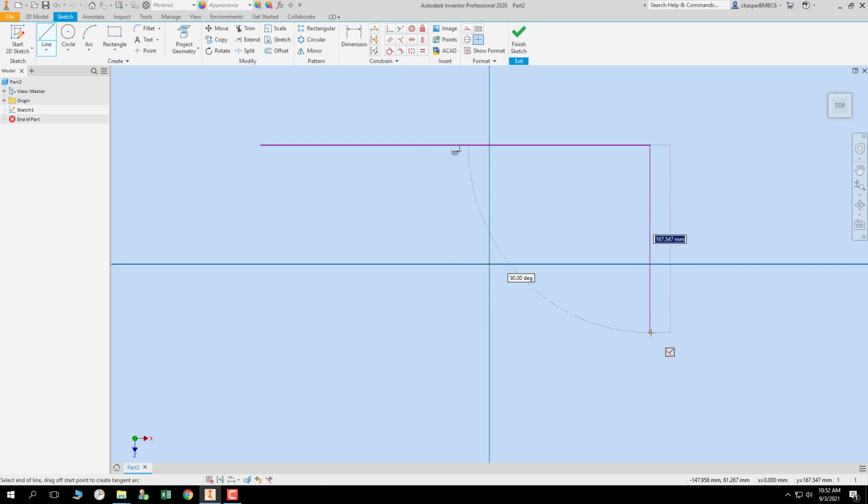Now this one I'm going to bring down here, and I'm going to make it vertical, or actually you see that it says 90 degrees. The length is 167 millimeters. This can be a big object. The next constraint that has come up looks like a perpendicular constraint. So if I look for that up under the constraints list of things, I see one that looks just like it right here. And that is a perpendicular constraint, which means it is perpendicular to that line. I believe this line.